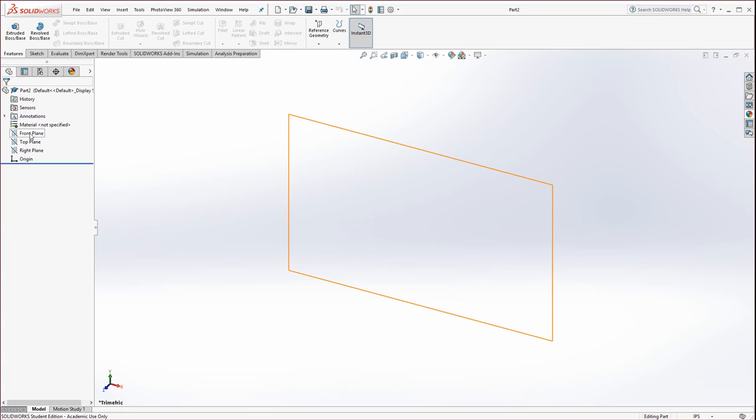But right now we're just going to go ahead, and most of these I just drew on the front plane for the most part. You select the plane that you wish to draw on, and try not to move your pointer too quickly because there's a really nice option that pops up. If you'll notice, I didn't move my pointer as soon as I clicked on the plane. And by the way, by clicking on, I'm left clicking.